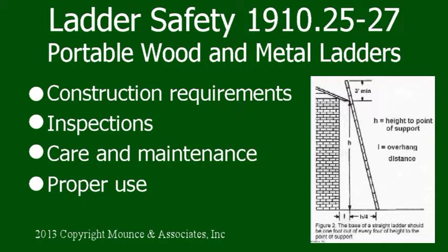When going up and down the ladder, always face the ladder and never turn around to go up or down. Always have your belt buckle in the middle of the ladder. Never reach beyond the ladder vertically or horizontally, as this could result in serious injury or death.